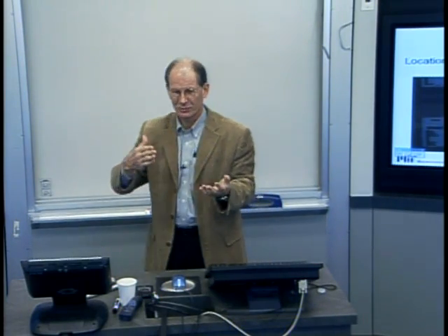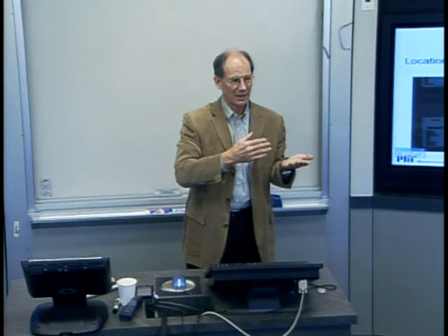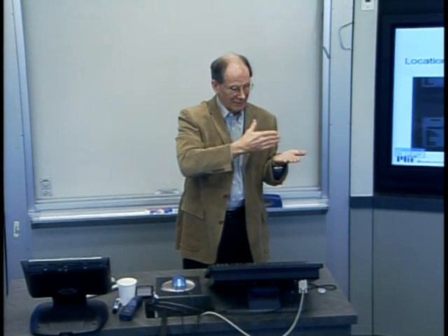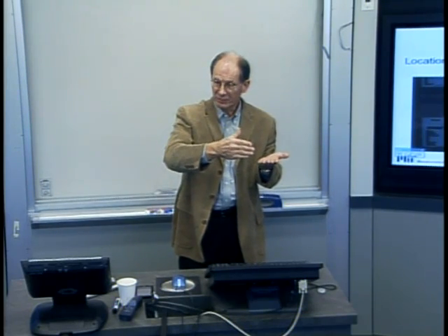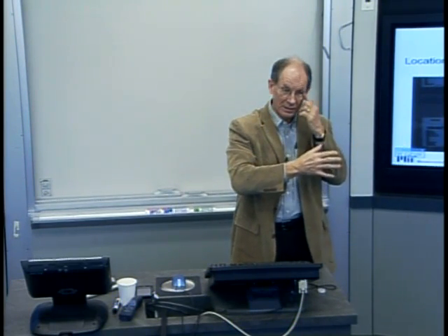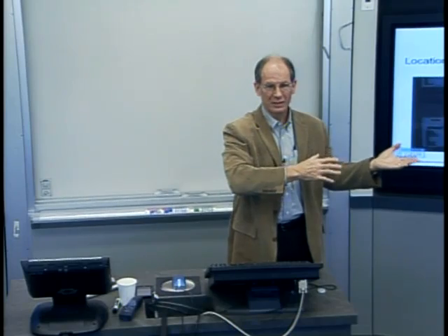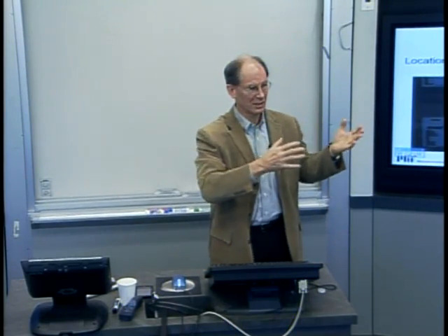Okay? And one of the things you want to think about when we're talking about manufacturing is always sort of question any statement of uniformity or constancy or things like that, because inevitably there will be variations because the topography of the substrate might change. Who knows? And in fact, it does happen, especially as you go to larger and larger wafers. You get important variations in the chamber, temperature variations. You could get concentration variations. All these kinds of things can cause problems.